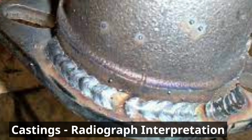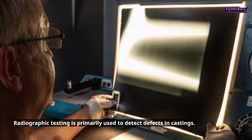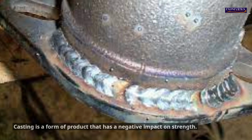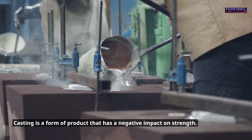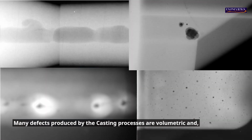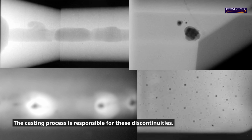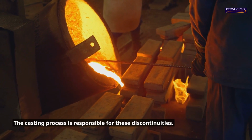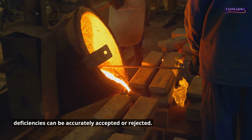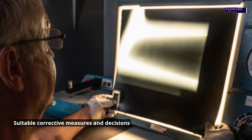Castings, radiograph interpretation. Radiographic testing is primarily used to detect defects in castings. Casting is a form of product that can negatively affect a product's strength. Many defects produced by the casting processes are volumetric and, therefore, relatively easy to detect by this method. The casting process is responsible for these discontinuities. If properly understood, deficiencies can be accurately accepted or rejected, and suitable corrective measures and decisions taken.